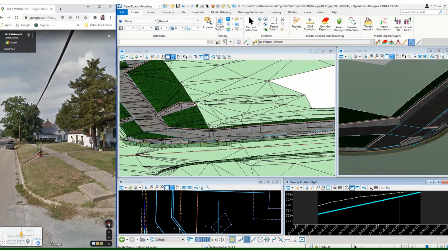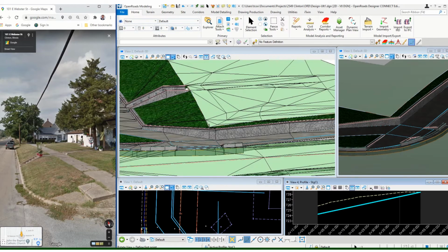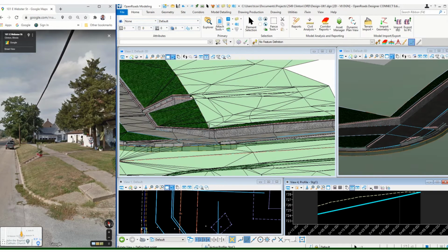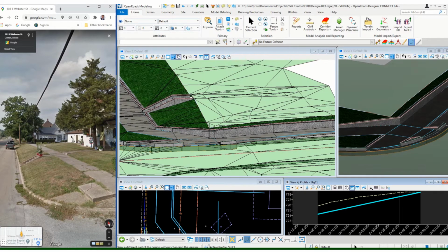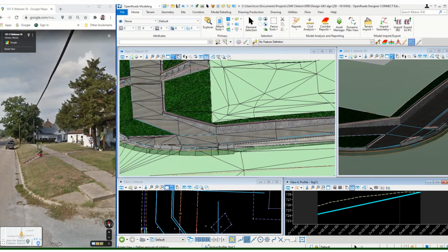And then from there, we need to get tied in by the existing right-of-way. So we can do that by connecting the top of this curb with the existing right-of-way, and that is 25%. So we end up with a 1 to 4 slope, which is completely acceptable.